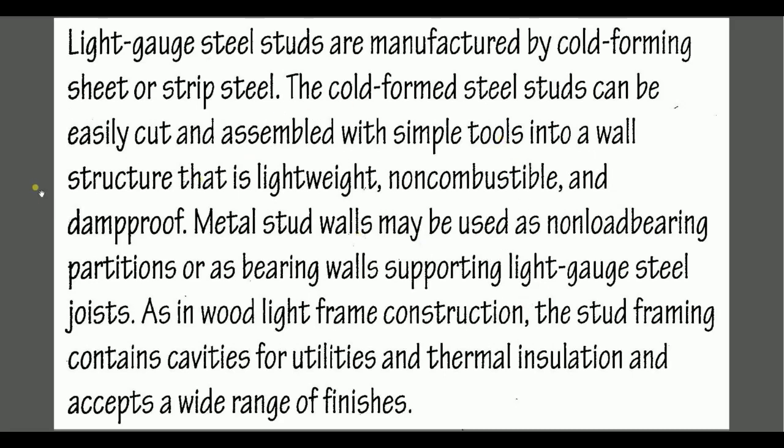So we can see the light gauge steel studs are manufactured by cold forming sheet steel, strap steel. The cold formed steel stud can be easily cut and assembled with simple tools into the wall. So you can simply use simple tools to install the light steel stud. The C channel is very light.